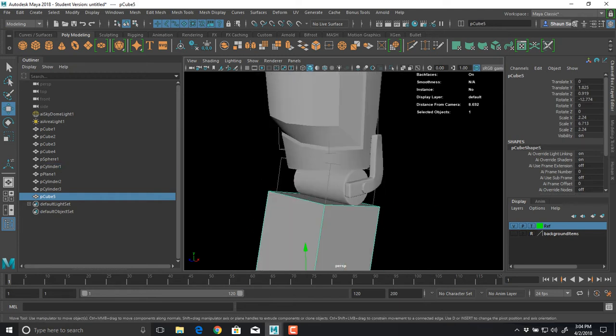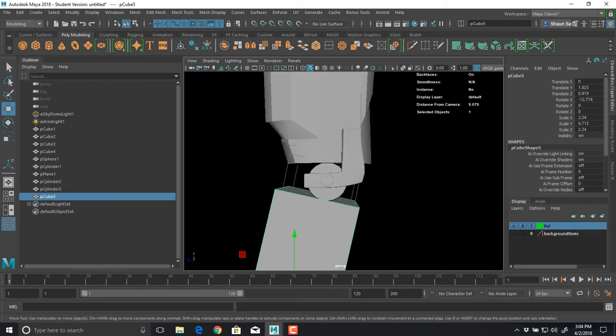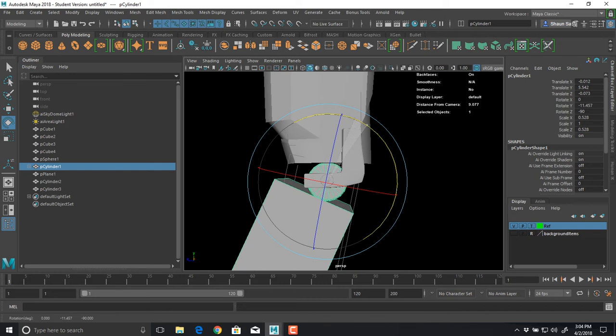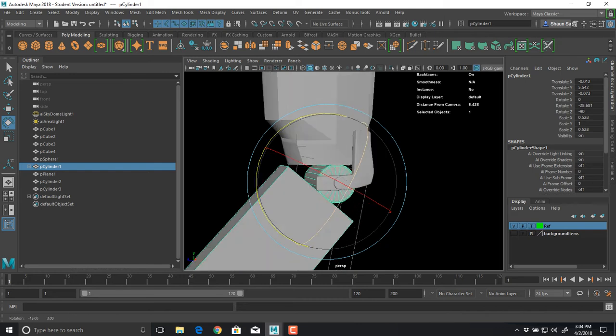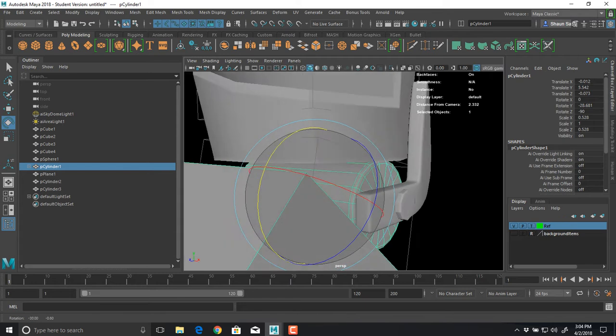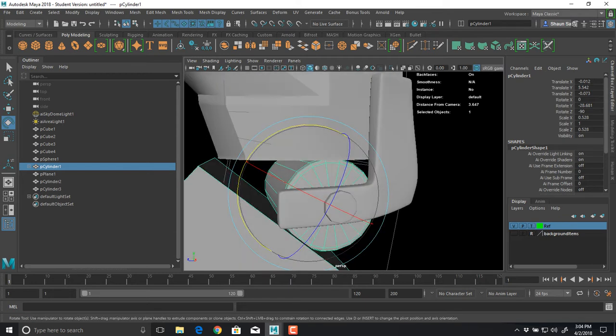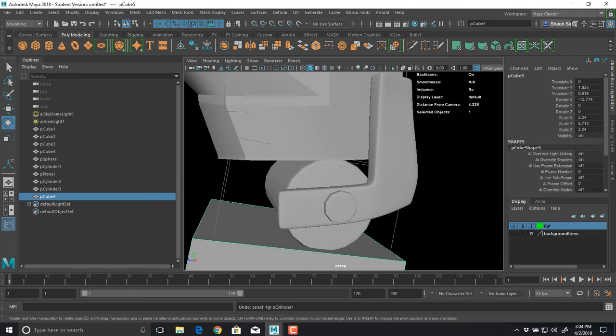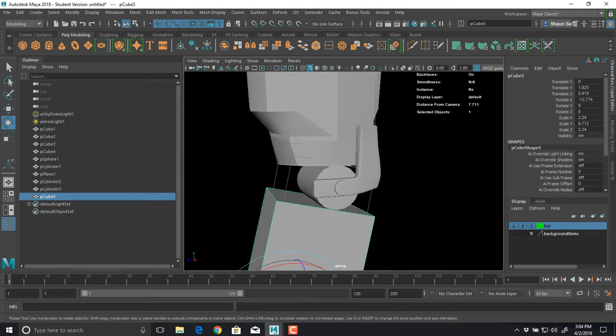Now I also have to keep in mind where this bracket comes out, that if this was to rotate, I'm just going to parent it to this gear so you can see it. As this does rotate, right about there it would stop, because this gear is hitting it right about there, this little bracket. Also, if I go up too far, it's also going to hit that. So that's stuff you have to be aware of, because at some point you may want to animate your item.